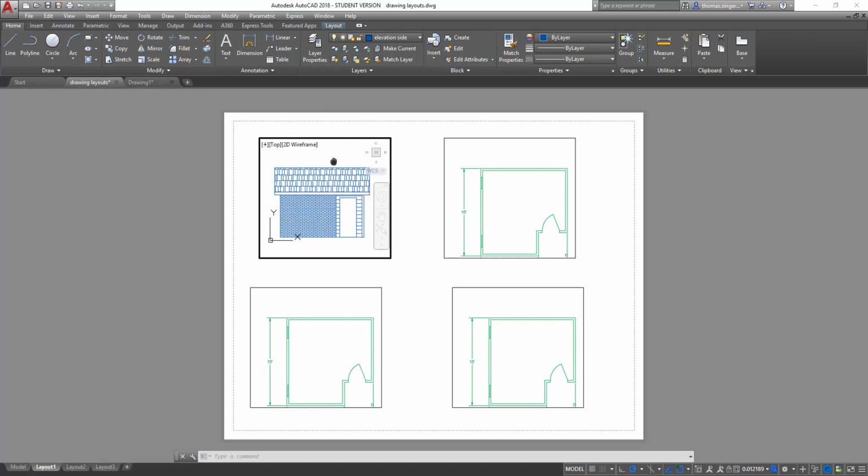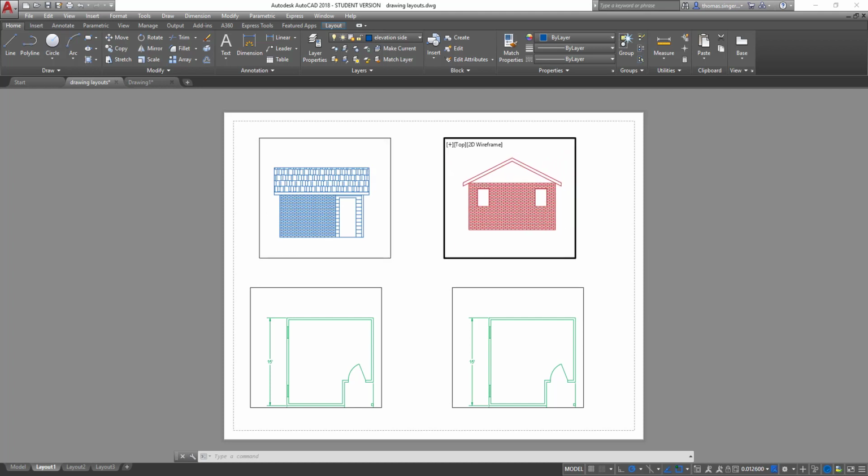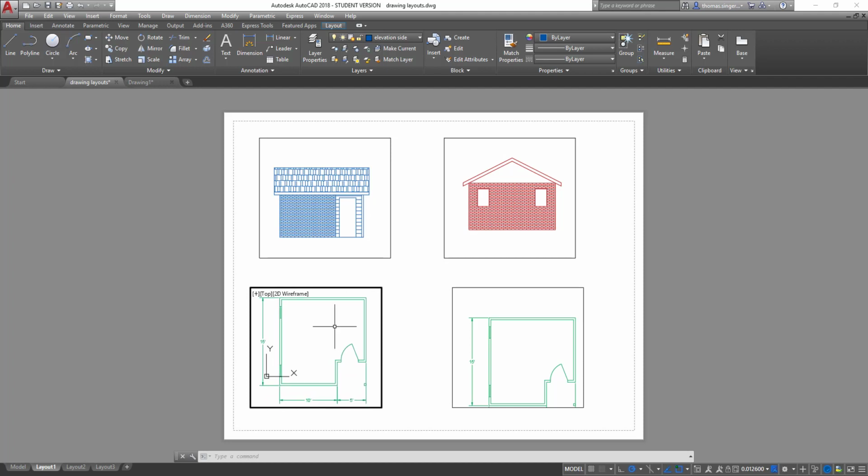So you can kind of get the idea of how I can set up a top, front, right side drawing by drawing the views, having them separated, and then creating 3 separate viewports between each one of these. So in essence, each one of these can have a separate image inside the viewport. And all I do is double click in to make that manipulation. And you'll notice that each one is independent. So even though I move this image, this one stayed exactly in the same position. So again, what we're doing is using the pan tool inside the window.